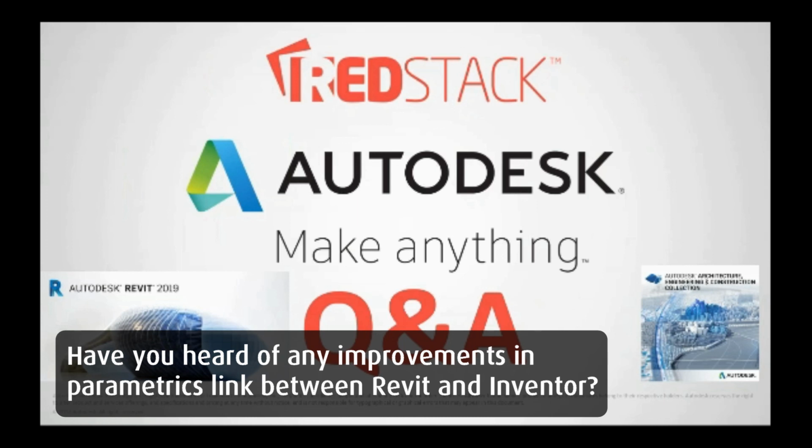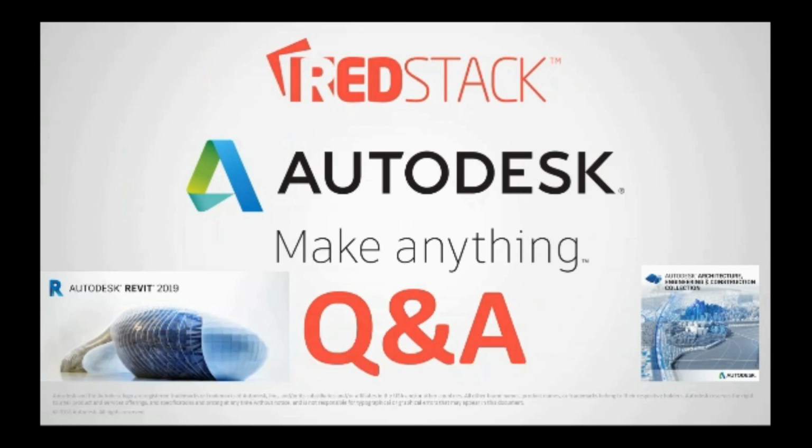So that'll give you a live link. That is the closest you're going to get to a parametric link between Revit and Inventor. The other workflow is through iLogic, so you could have an Excel form. Dynamo talks to Excel, Dynamo talks to Revit, iLogic talks to Excel. You change the Excel form and it should change through both, Gavin. We're automation specialists. If you want us to develop something for you, please reach out to me and we can discuss it further.